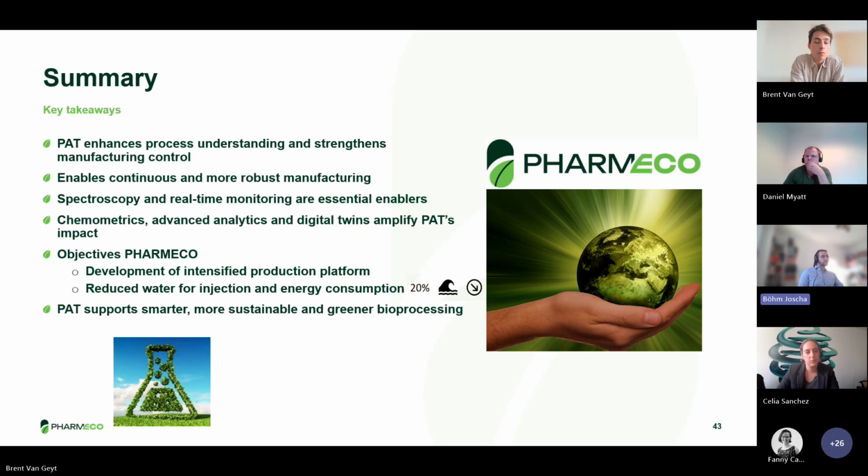On the process modeling side, you have options such as mechanistic models, where you can go for modeling with lower data, and there is a trend to develop models with as low effort as possible. There's also a trend looking into how we can reuse models and retrain them if the process has changed a bit, so that we don't need to gather all the data again when we go to some other process.